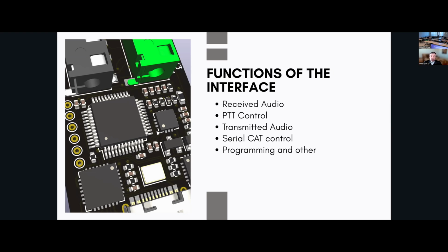And it's possible to do it through a command between the radio and the computer coming through the communication channel. Some of the radios support serial CAT control, on which we'll touch in a moment. But this is basically a communication channel other than payload, other than the audio. This channel allows the computer to tell the radio to tune to a frequency, switch band, activate, deactivate features, and things like that. So it's also possible to key up the radio through one of the commands if that channel is available in the radio and the command is supported.